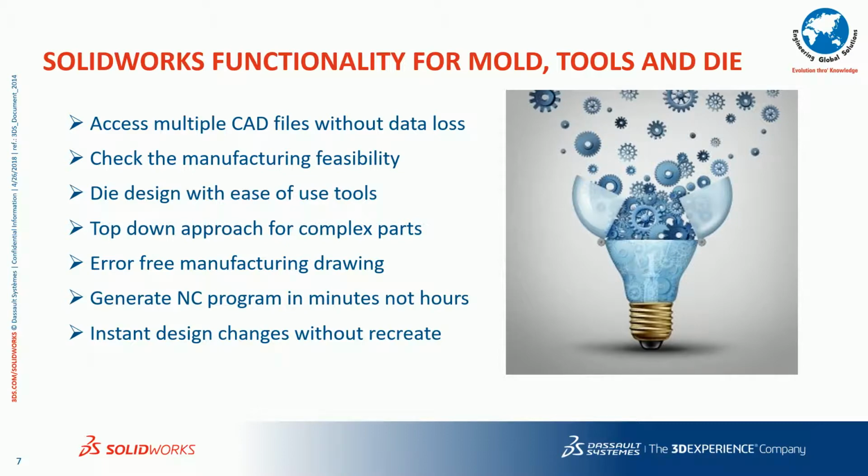We can access multiple CAD files from the customers without any data loss, without any translations. During your design stage, you can find the predefined analyses like draft analysis, undercut analysis, parting line analysis, everything. So you can do the top-down approach for complex parts that you are not able to do with the general mold tools. In that, you can do the top-down approach to make complex part mold designs easily.